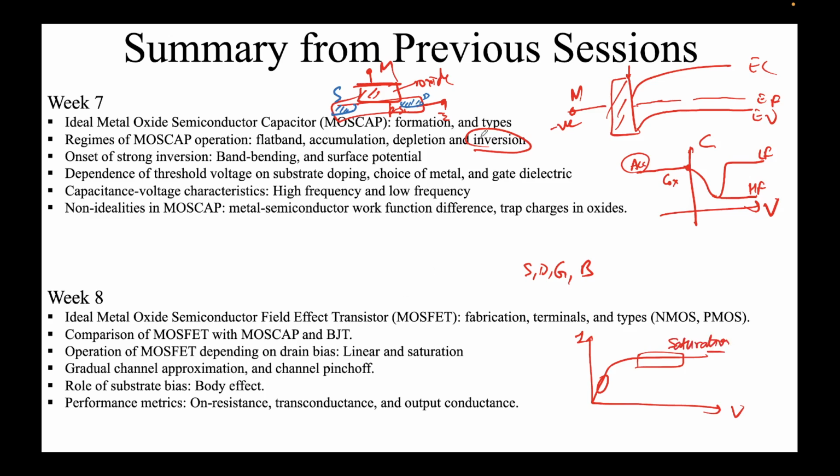And finally, the substrate here is usually grounded, the source is definitely grounded, but sometimes you can choose this body terminal, which is not grounded, to just change the threshold voltage. Because if you change the bias applied to this body, then effectively what is in your control is the threshold voltage, because now you can modulate the inversion layer from the bottom also rather than from the top, which is a very crucial tool when a circuit is designed.